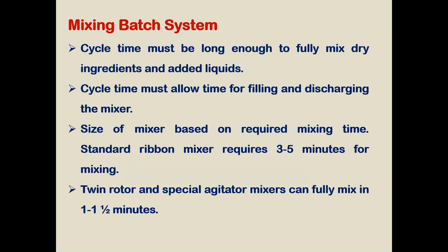Cycle time is very important for any mixer. The cycle time must be long enough for fully mixing the dry ingredients as well as the added liquid portion of either oils or molasses. The mixing accuracy of the mixture depends on the cycle time. How much time should be given for the cycle, and the cycle time must also allow time for filling and discharging the mixture.